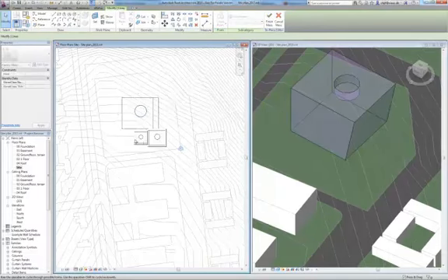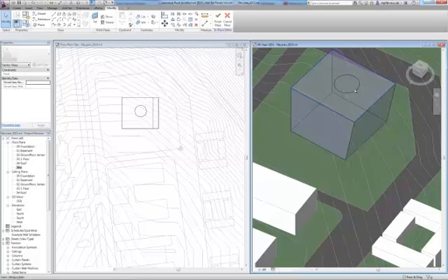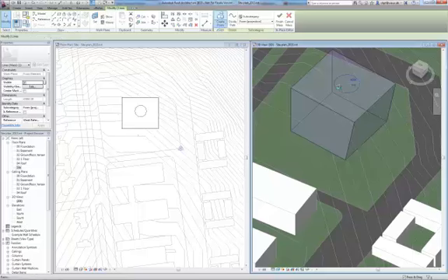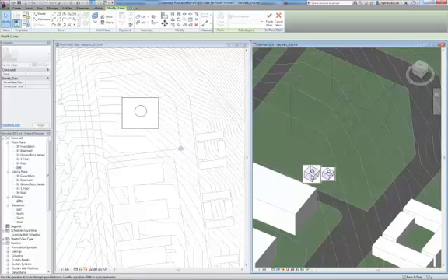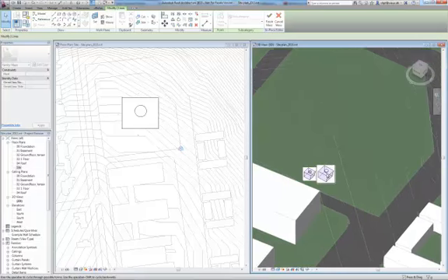You can have two options. It's hard to actually see on the 2D, so I'm just going to redo that one again, but over in the 3D view. Select my circle and create a void form, and you'll notice Revit will give you the two options here to create a cut into the object of like a cylinder, or like a sphere, so a round finish.